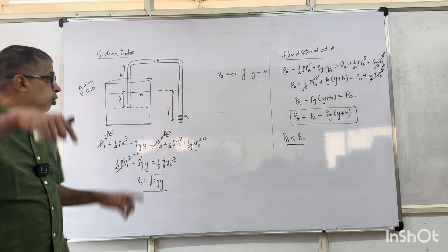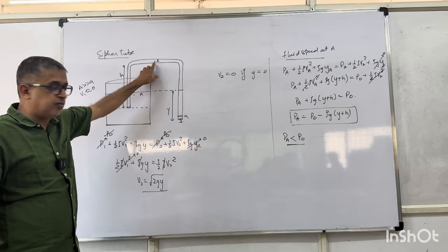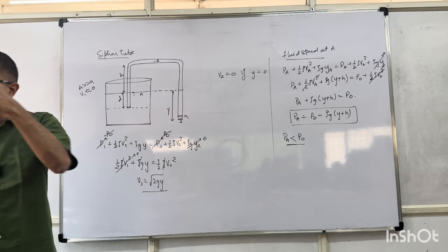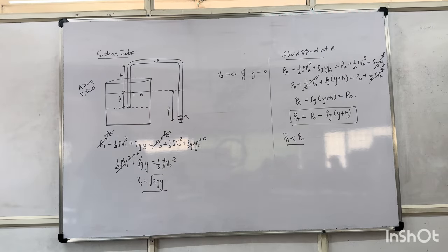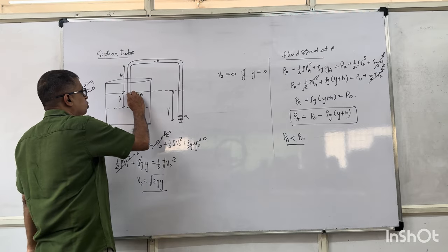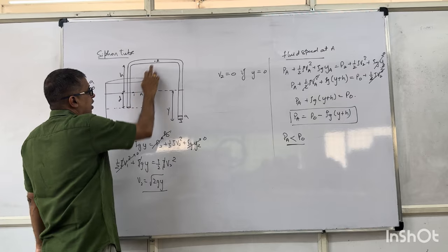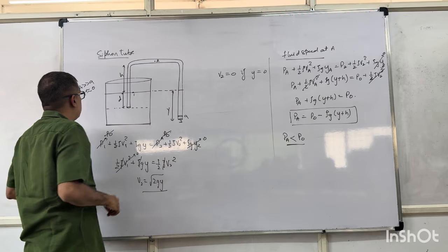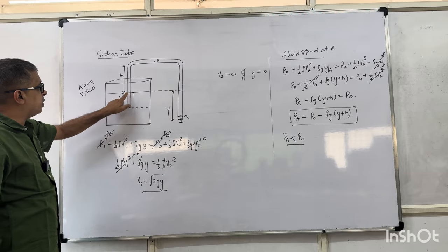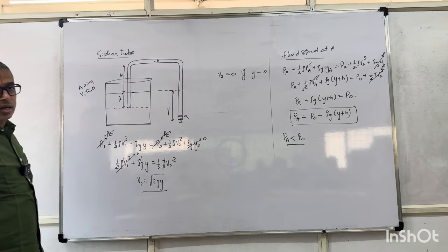Now that you have fluid filled inside this, you will have a particular point here in the fluid and a point here in the fluid for which you can apply Bernoulli's equation. Right? So the second part is the justification as to why pressure at A, this A and this A are not the same. This area of cross section, pressure at A is lesser than atmospheric pressure. So this will push the liquid this way and by default it will keep coming out.